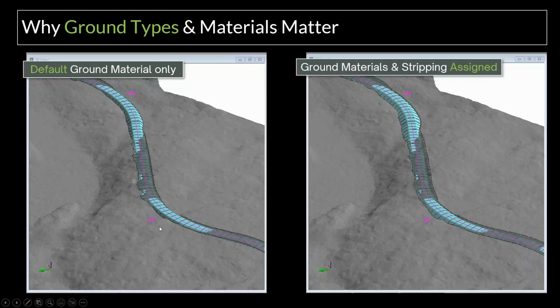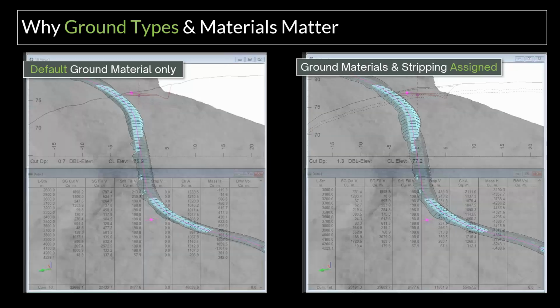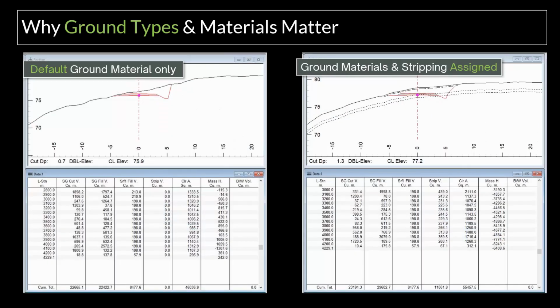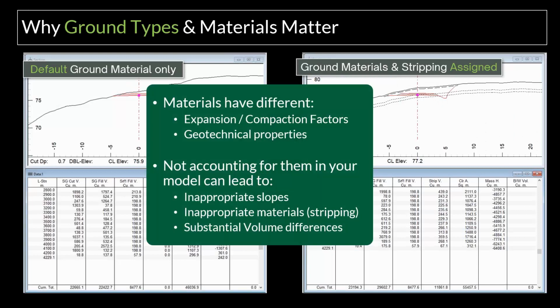If we consider how that's going to affect things from a boots on the ground perspective, if we were laying out those slope stakes, we're going to be off a little ways from what should be there depending on the material we have assigned. This plays a bigger role when we get into the nitty-gritty. At a specific station, it might not seem like it makes much of a difference, but when you do that over your entire road, it certainly adds up.